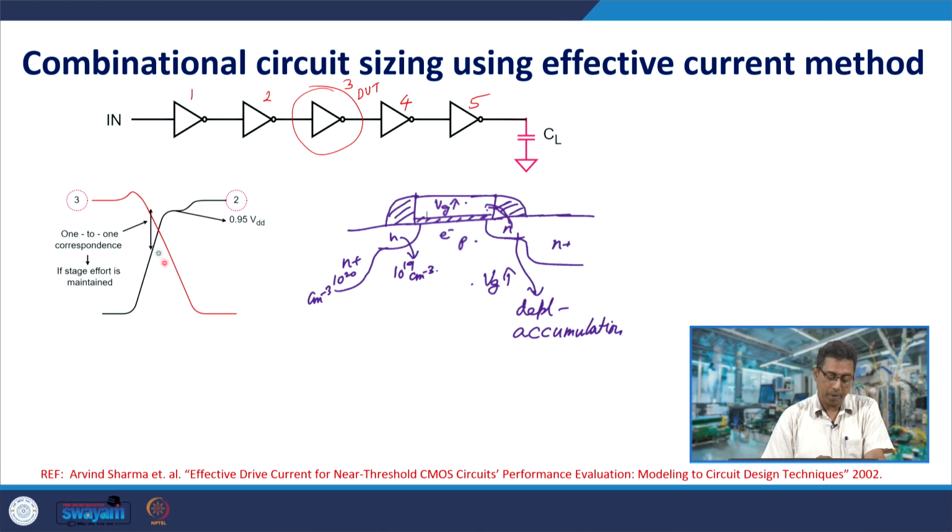During the major part of the discharge, the input voltage value is not VDD, it is slightly lesser than VDD in planar technologies. In FDSOI and FinFET technologies, we will observe that the discharging voltage, or switching voltage, is even smaller than 0.795 VDD.